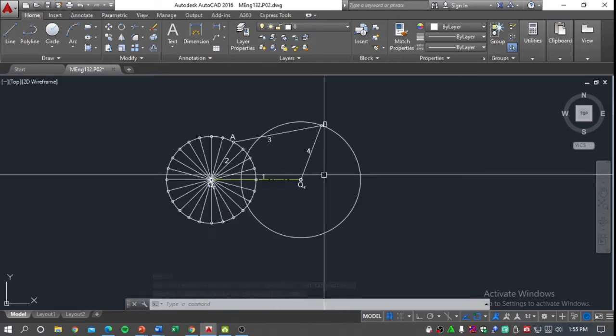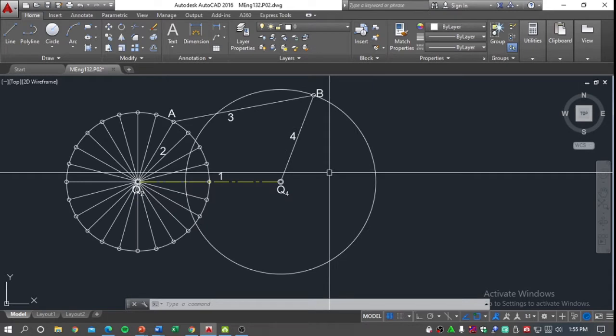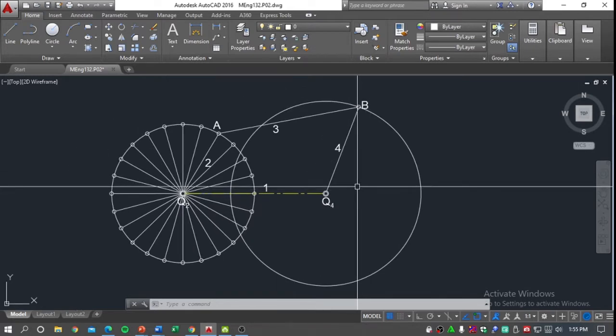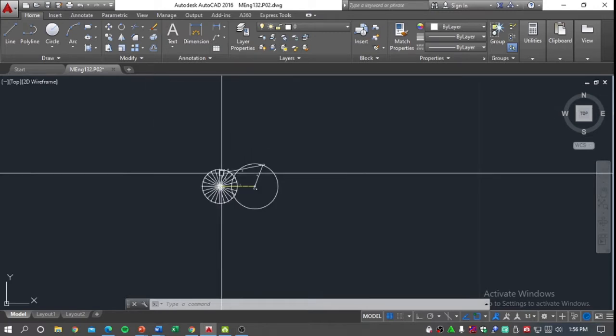So this is only a projection since we know that point B only oscillates a certain angle, and since Q sub 4B is longer than Q sub 2A, it indicates that Q sub 4B only oscillates, and the shorter one, the Q sub 2A, which is the driver, is the one that can complete a single revolution.